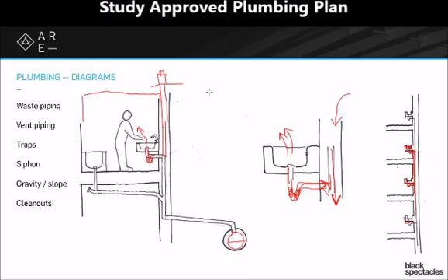You also have to make sure that the vent pipes are sloped in the opposite direction, so that as that condensation, that fairly unpleasant condensation, starts to find its way to the walls of those pipes, there's always a way for it to drain back down and eventually find its way to the main waste pipes. So everything is angled in such a way as to always be draining positively.